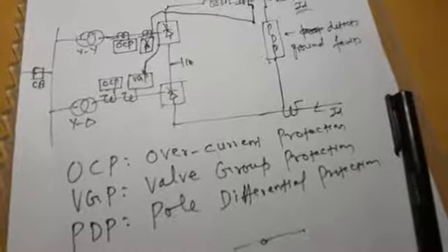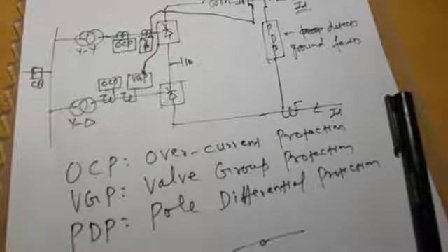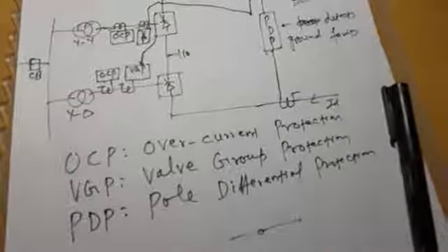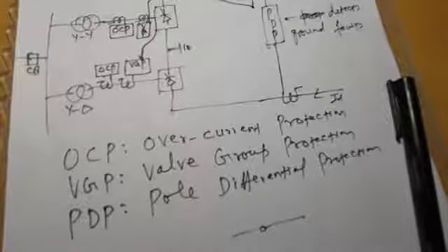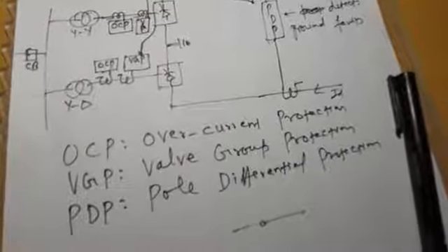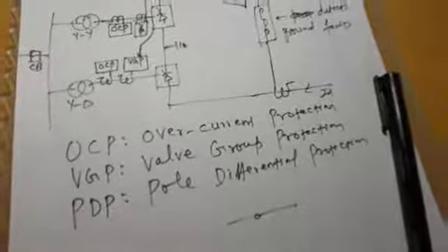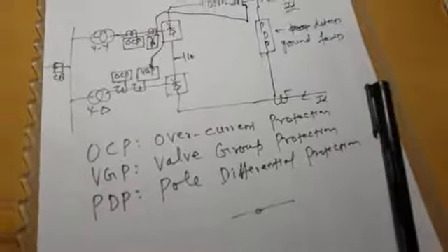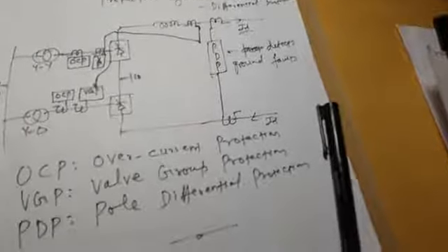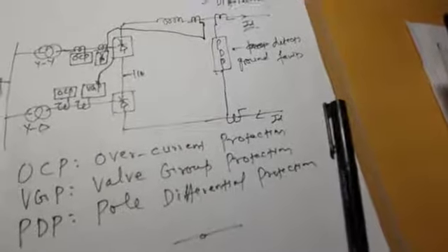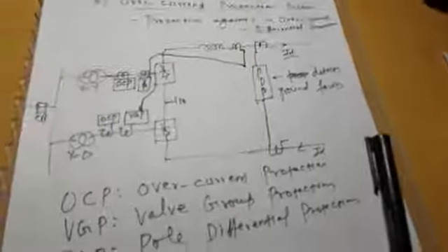And how do you provide protection? By using overhead ground wires, or by protective gaps or lightning arrestors. Now, what type of protections do you have to provide on the DC side? In your HVDC converter system, or in your HVDC converting station, you need protection against overvoltages, which is similar to protection against overvoltages in the AC system with some minor differences.